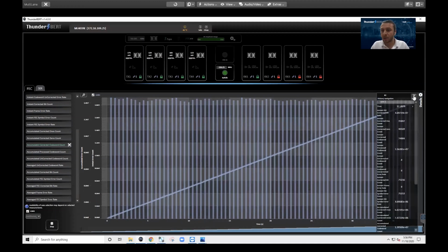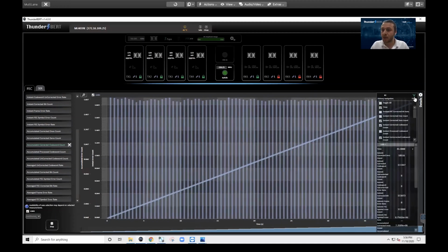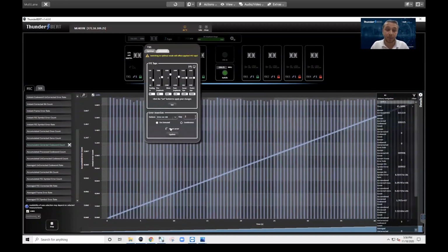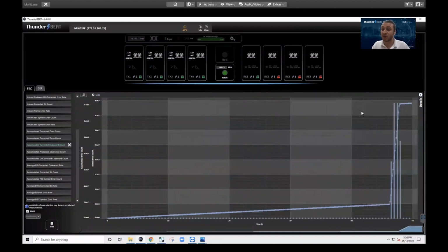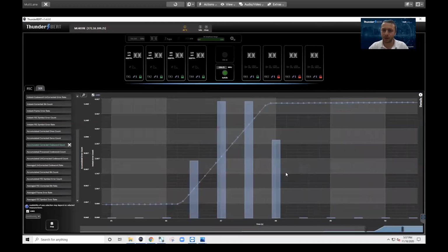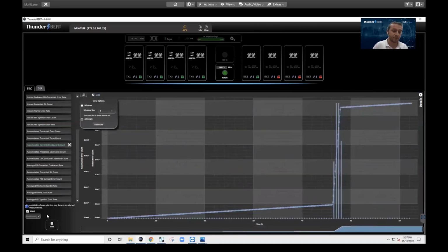So once again, we can choose to filter which measurements we want to take a look at. We can go ahead and apply history navigation. For example, if I apply that same error burst to a FEC link, you'll see that rate of code words that are being corrected shoots up to a very, very high value right over here. And again, I'm zooming in to use my history navigator to see what's going wrong here, or I can go ahead and auto scale and I'm back to the main page.